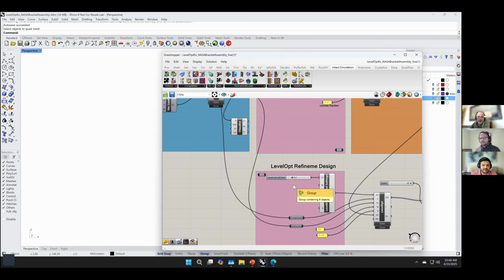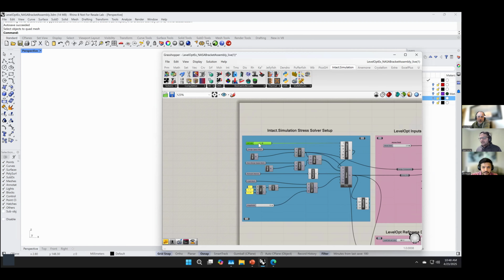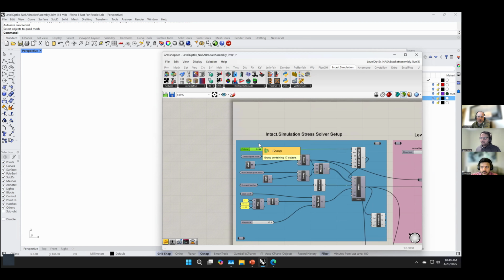I think it really depends on the model, the geometry, the size of the geometry. And if you don't know it, in FEA you just have to do a convergence study. So you keep changing the resolution or the cell size, decrease it slowly. And when you see that your displacements are leveling off, flattening, that means you have reached convergence. Otherwise, if you know exactly how many elements you want in what regions, then you just directly pick the cell size.